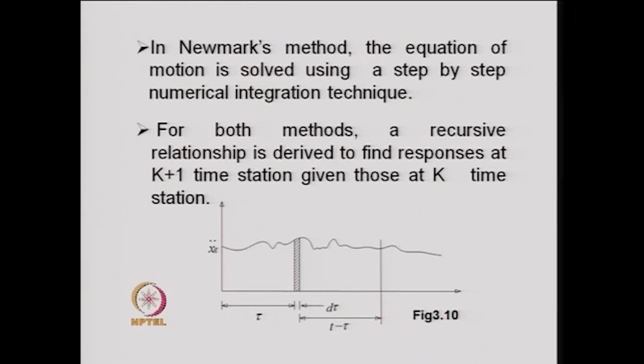Let us take the Duhamel integral first. As you know, in a Duhamel integral, we consider the load to be a series of impulses, and for these series of impulses, at any time t, we see what response we obtain and then sum up the responses for all the impulses to get the final response at this particular point.